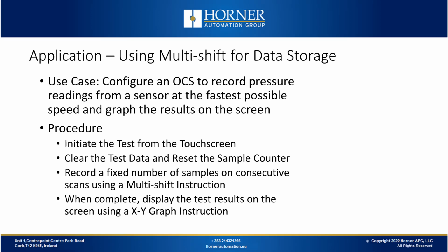By using a multi-shift instruction, I can build a ladder routine which allows me to record data every single scan for a certain number of scans and display it on the screen. To do this, we need to put a push button on the touchscreen to allow us to initiate the test. The ladder logic will clear the test data and reset the sample counter. It will then record a set number of samples on consecutive scans using the multi-shift instruction. When it's finished, it will display the test results on a screen using an XY graph instruction.